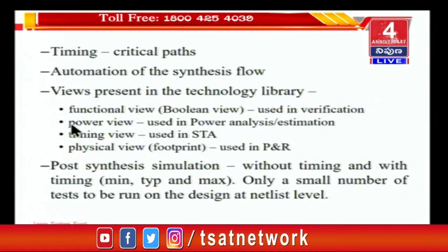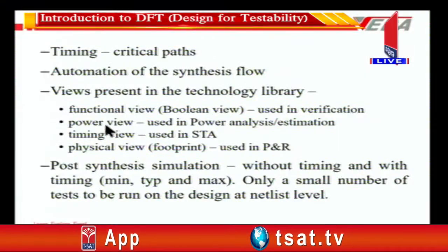Now there was one question which came to me: what is the use of these parasitic capacitances? Parasitic capacitances are not introduced there in order for the functionality to get improved or anything like that. They are unwanted capacitances, but they are present because of the construction nature of the semiconductor circuit, and their adverse effects need to be overcome. We have to live with it. There is no way of wishing away the parasitic capacitances. They can't go to 0. So that is the power view. The third, very important, is the timing view.